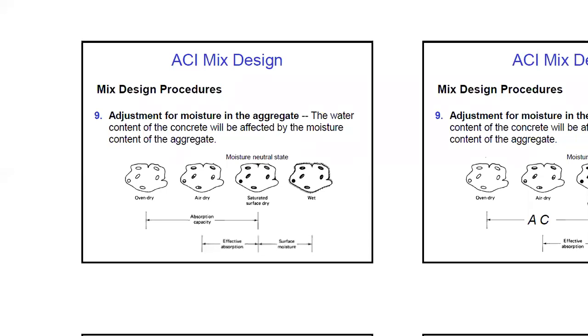The ideal condition is going to be saturated surface dry, but if you are having an aggregate which is in wet condition, or in dry condition, we have to adjust the water content according to that condition as well.